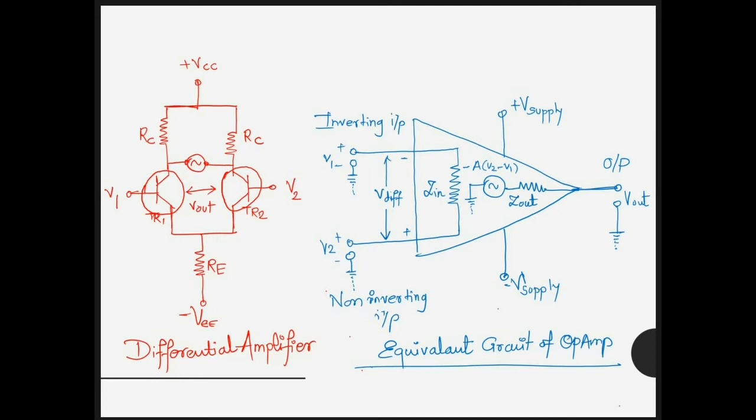Operational amplifiers also have one output of a low impedance that is referred to a common ground terminal, and it should ignore any common mode signals. That is, if an identical signal is applied to both the inverting and non-inverting inputs, there should be no change to the output. However, in real amplifiers, there is always some variation, and the ratio of change in the output voltage with regard to change in the common mode input voltage is called the common mode rejection ratio, CMRR.